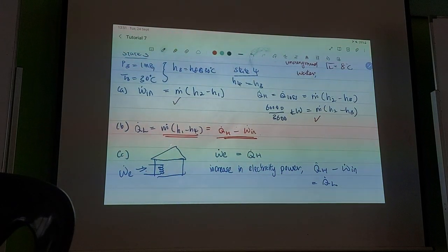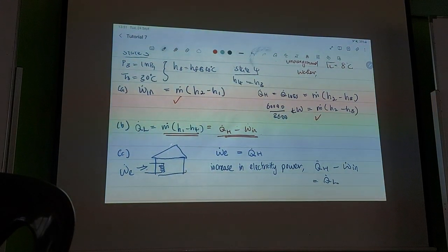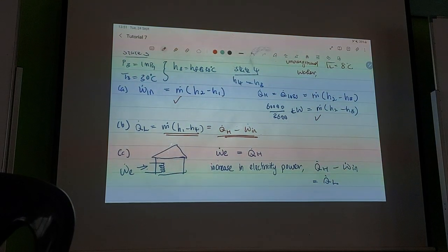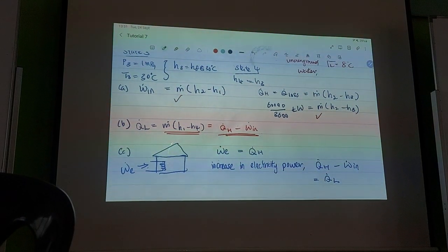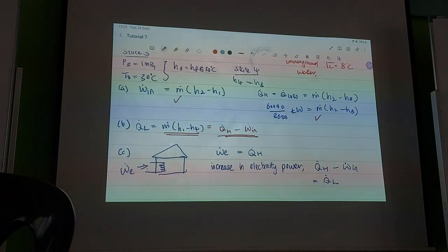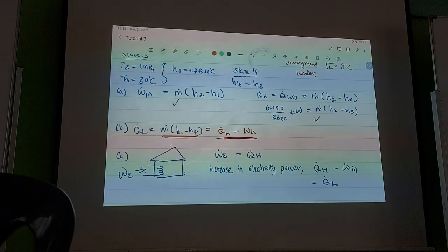So in a country like ours, using a resistance heater will be more worth it because you don't really need this all the time. If you have 4 seasons, then yeah, a heat pump will save a lot more power in comparison.